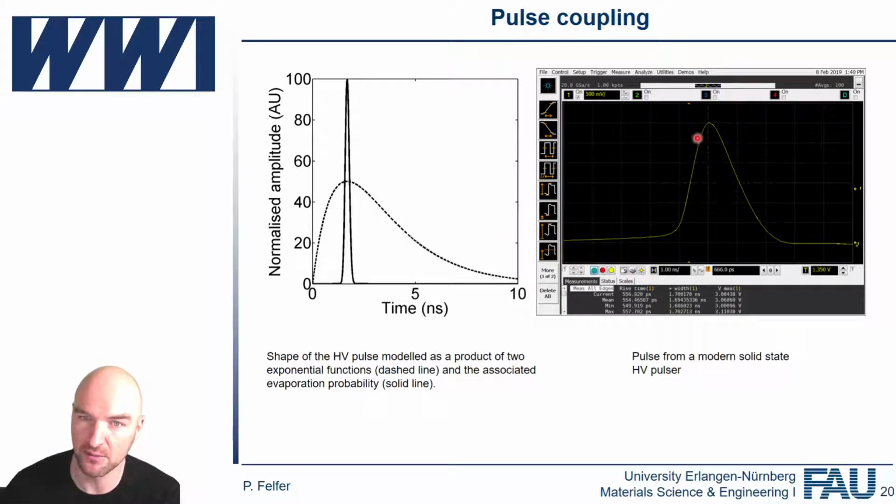They look a little bit like the one here. So this is actually our 200 kilohertz, 3.5 kilovolt pulser that we're using on our Oxcart atom probe. I hope you can see that well, but one division here is 1 nanosecond. So you can see the pulse has a full width half maximum of about a nanosecond and a half, and a rise time of about 550 picoseconds. If you think about it, that's 550 picoseconds for 3,500 volts. So this is an extremely steep rise in voltage.